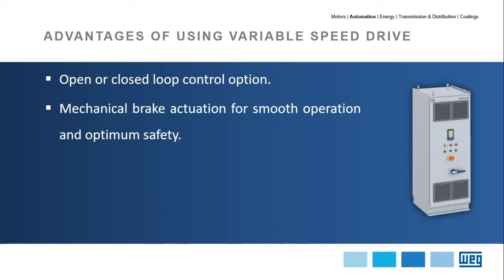Here, I want to give special attention to this topic, mechanical brake actuation for smooth operation and optimal safety. As you are aware, every crane application requires a mechanical brake to stop the motor, and the VSD is able to control the braking system of the motor as well, the actuation of the brake. Automatic brake close if a fault is detected. This is another advantage that the VSD can handle as well.